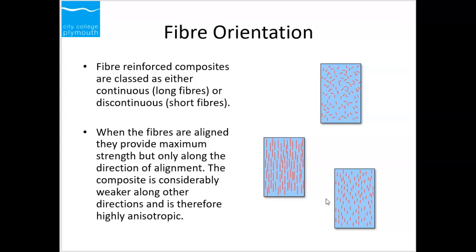because in terms of an aeroplane, say we have an aeroplane wing, we want strength in only one direction. We don't want strength in all directions. We can figure out which direction the load will be applied, and if we know the direction of the applied load, we can make the composite strong only in that direction. Why? Because the major advantage of composite is weight reduction. Fibers are quite heavy. We can add the fibers only in one direction, and then we will get the strength